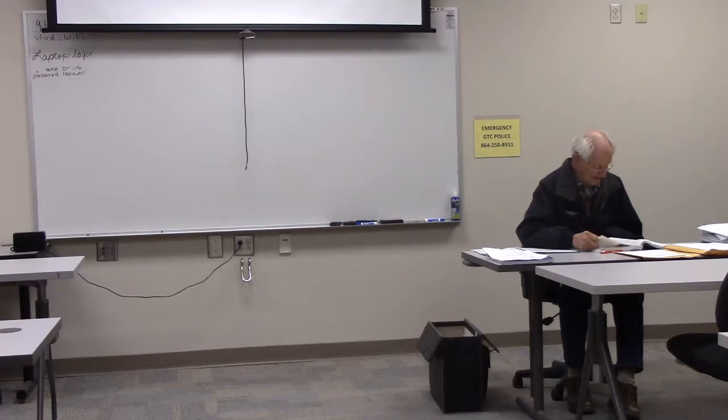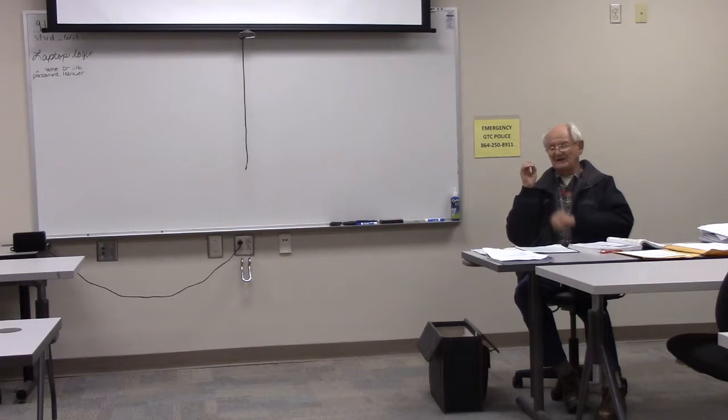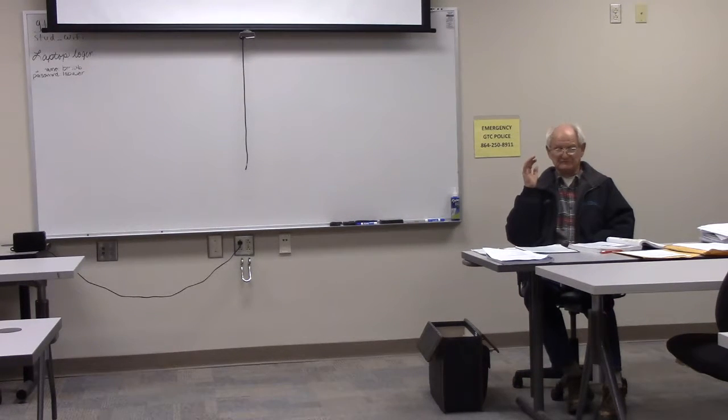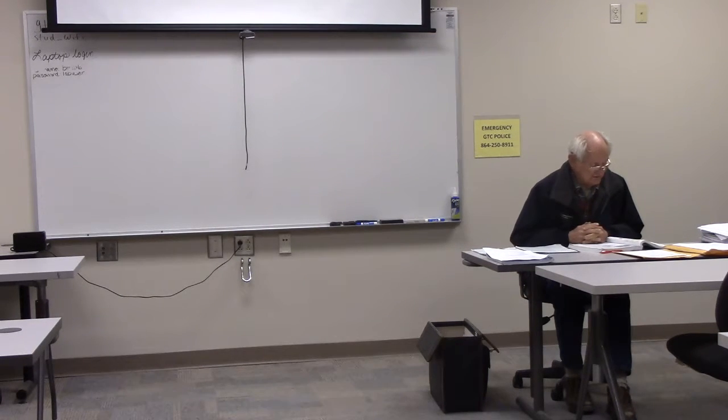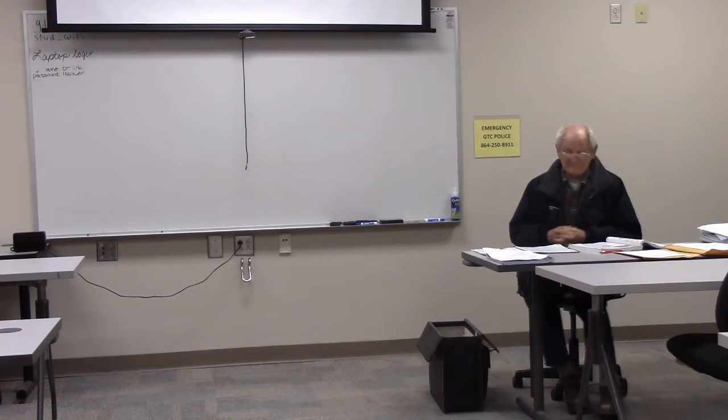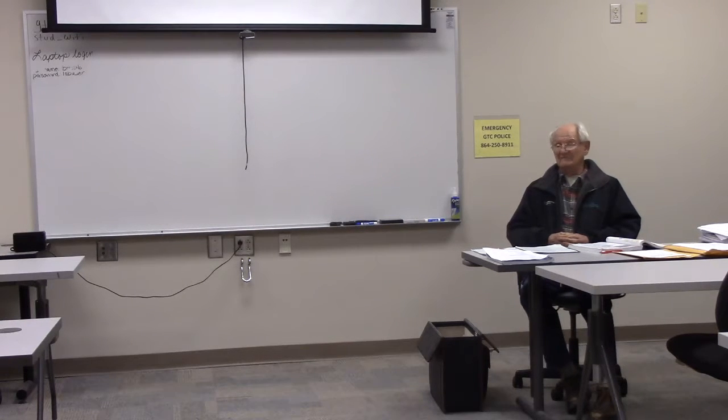All right. Figure 5 on page 5 shows a shallow box being used with a fixture. And that fixture has a cover that allows space for making it up. So the National Electrical Code section 314.24(A) requires that this and all boxes have a minimum depth of 1/2 inch.